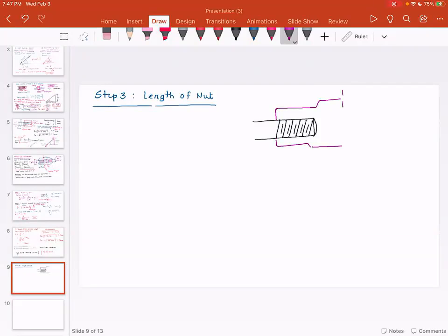And imagine you have the same assembly on the other side. So consider that there is this load P, and then there is this load P. Now, if you look at the way this nut and the rod assembly, or the screw assembly, could fail, it is if at the nut and the screw interface there is interface crushing.